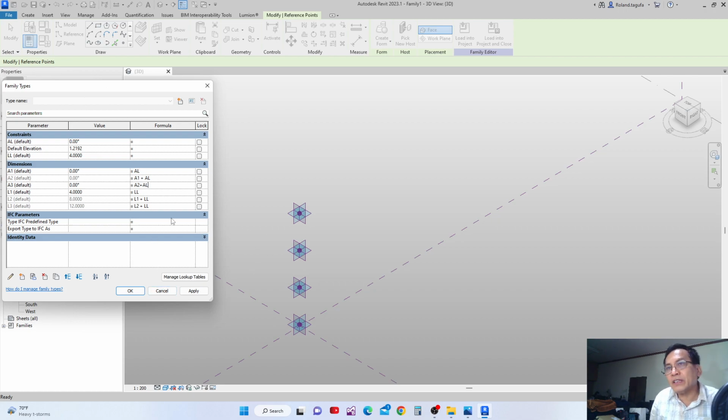And then let's check if it is flexing. I'll change this to 12 degrees. Apply. Now it's flexing. Or make it 30. Apply. Now it's flexing. And then go back to 0. Apply.